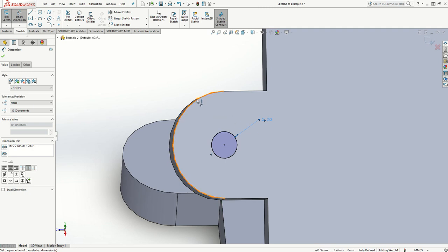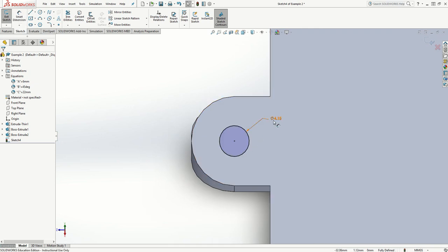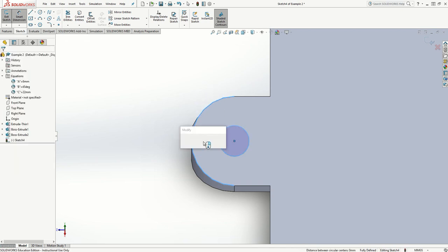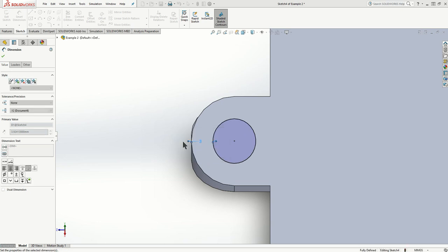I think something's wrong with this one. It's not, it's a distance, that's what I figured. So it's not this one, we don't want the diameter here. We want to make sure we have the distance from here to here. There we go, this is what I want. And now we're going to do it equal to A divided by 2, which is giving us this, makes more sense.